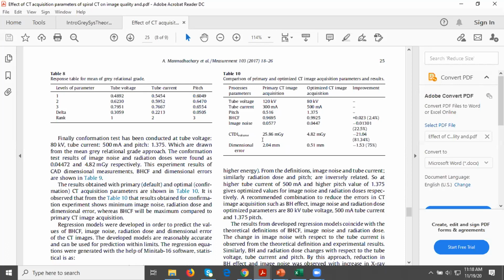Okay, instead of the 2 mm error that was there previously, now we are getting only up to 0.51 mm. The 2 mm is not a big issue for the medical community, just for the printing they are giving. But for manufacturing a single implant, very high accuracy is required, 0.5 mm, because the CAD model you are having has a 2 mm error. When we are going for manufacturing the implant, once you are getting 2 mm error, 2 plus 2, it becomes 4 mm.